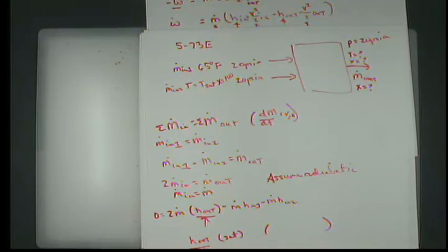The basic process of solving here is to find H sub out, and then you need to have one more variable in order to fix the state. So you have to have either temperature or pressure. So after you find H, then you have T and P, you're going to be able to solve for X. So that's the process. Yes? I know you already said this, okay, but how did you say to find H sub out? Right, because it's steam, H is in the tables.